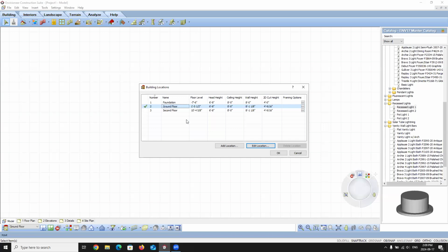The wall heights recognize what they were inserted at, and they are kept at that value. So just to give you an idea of some of the independent versus interactive, I'll just go over them again so you have an understanding. The number and the name are not interactive. It's not going to change anything in your actual drawing file, so you don't need to worry about those. Adjusting your floor level is interactive. So if I adjust the floor level, it will update my model for me.